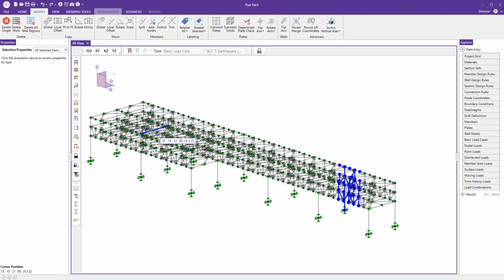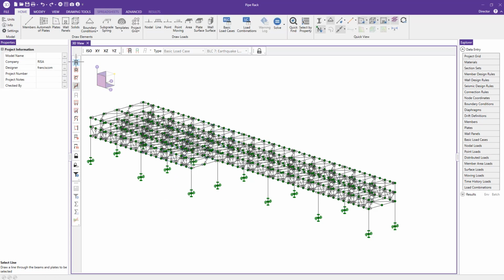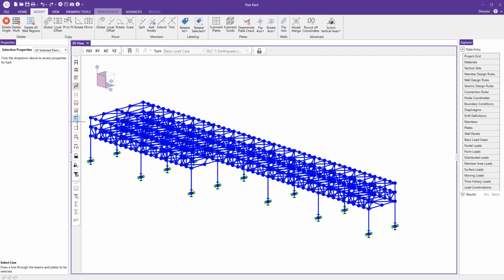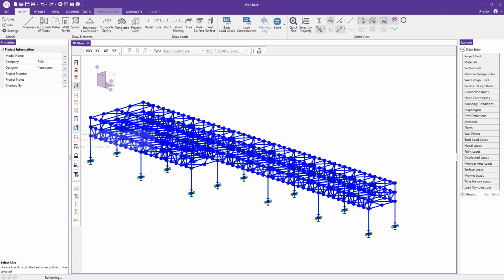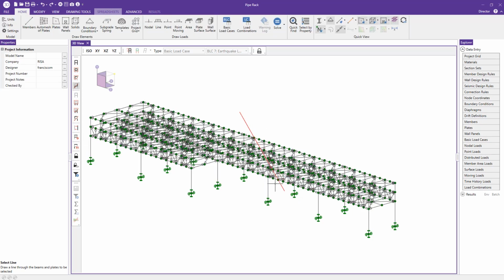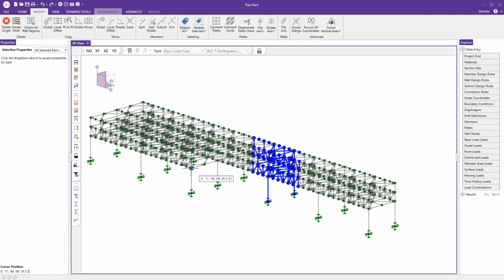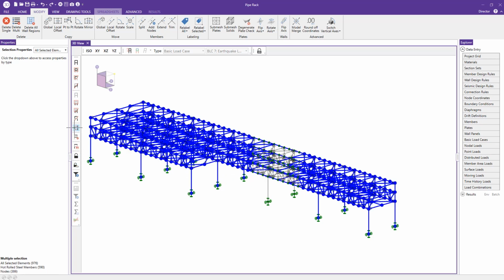Okay, and then we also have our legacy features for striking a line through elements. If I click here, everything that was intersected by that line is now selected. You have a quick unselect all, and a quick select all tool as well. Then you can invert the selection by using our invert selection here. Maybe if I click and drag to grab a few of those elements and I want to invert the selection, I could use that tool to do exactly that.